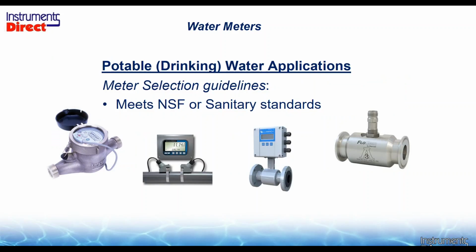You have a potable water application, okay? And step one, what you have to have with a potable water application, like we said, is that certain meters have to be NSF certified. In this case, this particular water meter meets the lead content requirement, and this is the kind of meter that you would have, say, 3/4 inch to 2 inch on the outside of your house, and it has the traditional odometer type meter on the top. This is what you would use for a budget type flow metering, just for general inventory purposes. And then you could expand from that. You have a clamp-on ultrasonic flow meter. It's on the outside of the pipe.